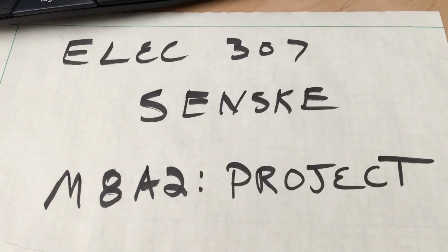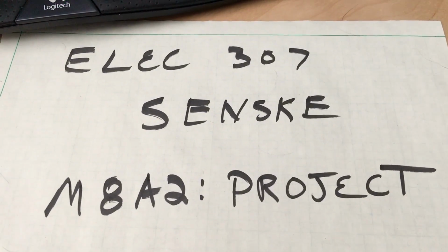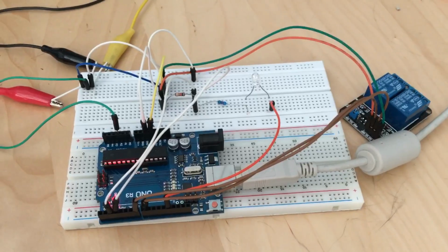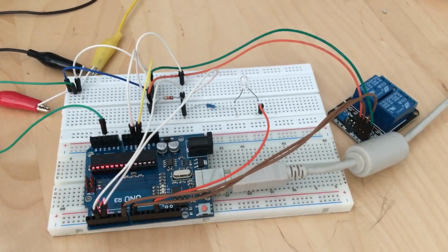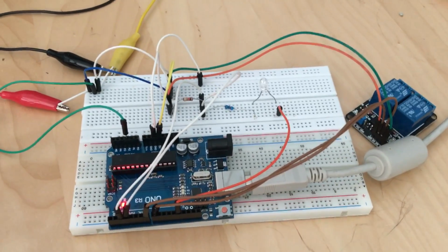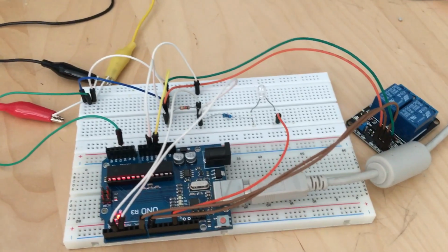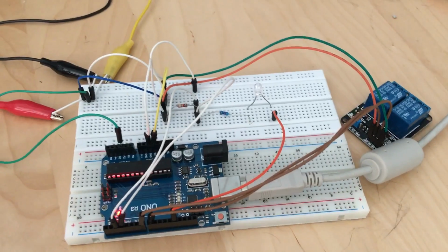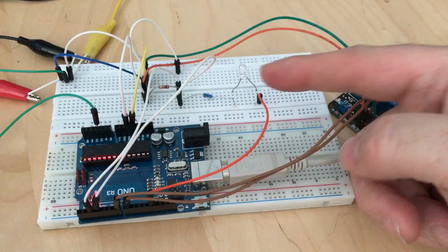This is my final project for Module 8, Assignment 2 for Microcontrollers class. My project is a sprinkler controller that has intelligent inputs for sensing ground saturation or water. In the event that there is a ground saturation condition or rain, the microcontroller sets a rain delay and indicates to the user that a rain delay has occurred.